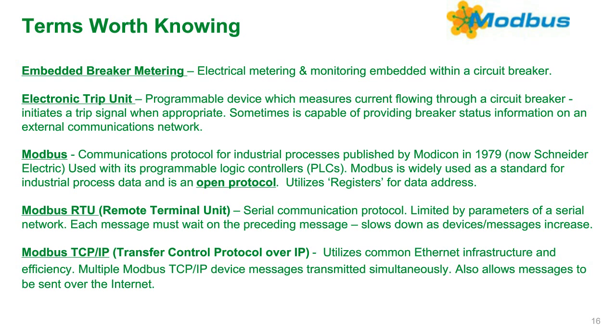When we talk about Modbus TCP/IP, that's Modbus on Ethernet, a lot of those problems go away because with Ethernet, many messages can run simultaneously. You don't run into that problem of messages getting backed up. So you have a more effective and a more efficient way of transmitting multiple messages at the same time with Ethernet. So Ethernet was obviously introduced at a later time, and Modbus TCP/IP is utilizing that Ethernet capability.